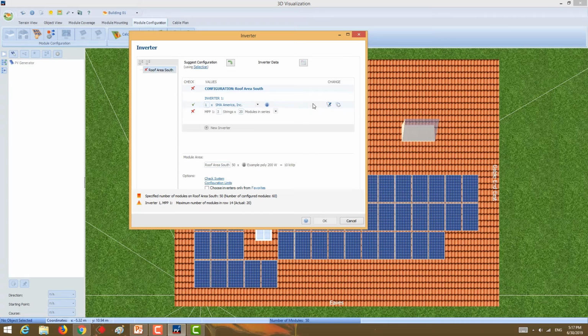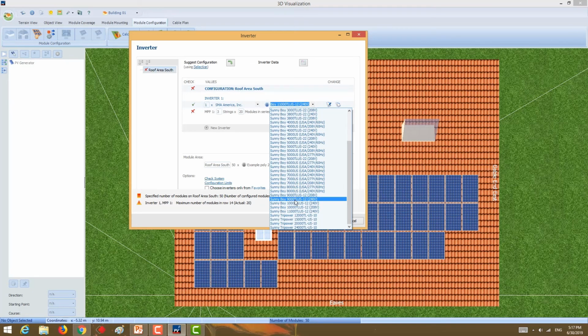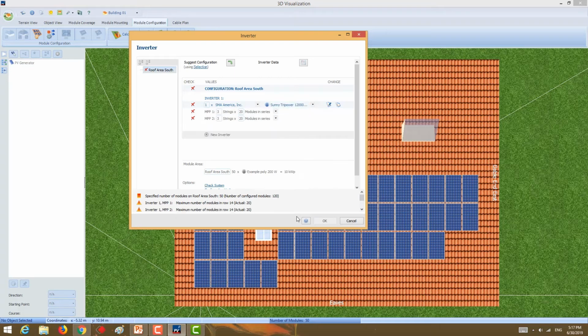We're searching for a module or an inverter with more than 1 MPPT, something like this. So we have 2 MPPTs here. I would choose 3 strings with 14. It means that 42 and 1 with 8 modules. Is it possible again? No.